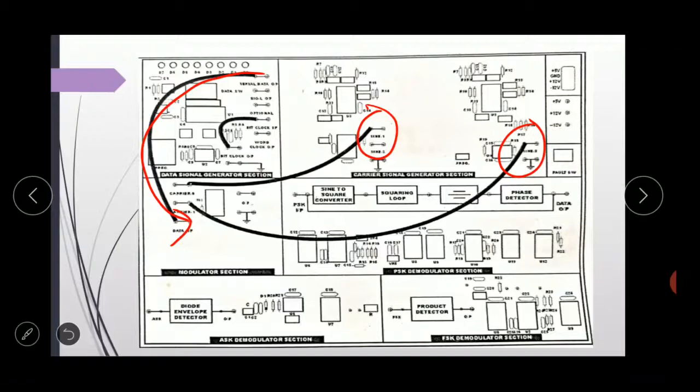The FSK modulator is built around the 2:1 multiplexer, which switches between the two signals for all 1 to 0 transitions. Here at the output we observe our modulated signal.